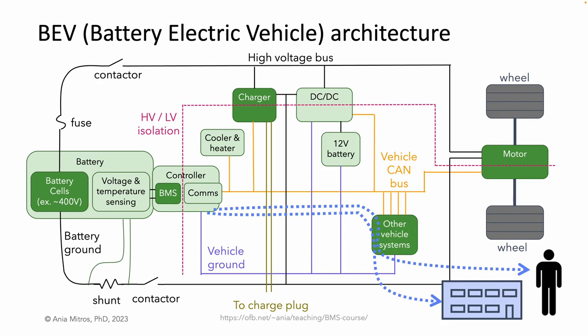For example, my Tesla automatically turns off Sentry mode, which is the car alarm, when the battery reaches 20%. Cell temperatures are also an important BMS measurement, letting the BMS detect when the cells are too hot, too cold, or just right. To keep them in the just right range, the BMS communicates with the heating or cooling system.